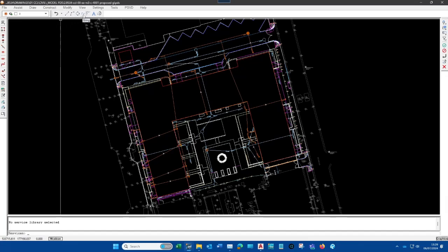I will just quickly dive into what a string and a line is, because if you use CAD, it's either line or polyline. Line is just a single line segment, point A to point B. Polyline is points A, B, C, all the way to Z, and everything in between. String is the same thing. It's a whole bunch of segments joined together.